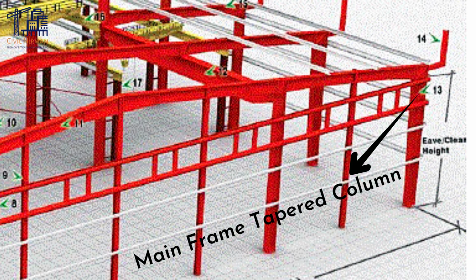On number 13 we have main frame tapered column. See, column and rafter connection. This is as per choice of engineer and functional need of framing system. Column to rafter connection can be designed in various methods. In each option of rafter column design, there are different merits and demerits, as steel consumption also keeps on varying in each option. Therefore, it is necessary for designers to opt for economical connection unless some functional constraints are there. As a standard practice, ease of erection and economy, in the following priority, is recommended. So let's see few of the typical column rafter design details.